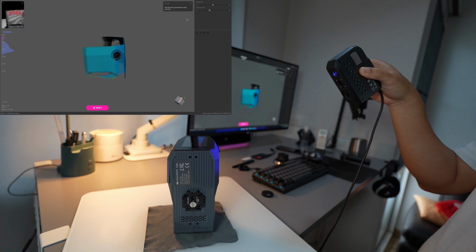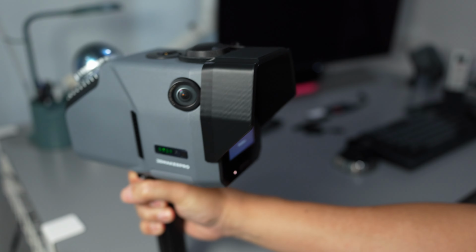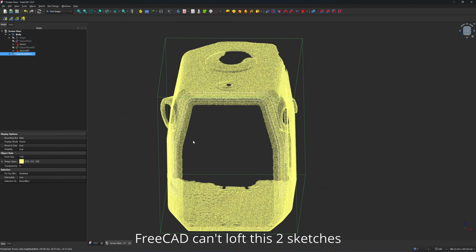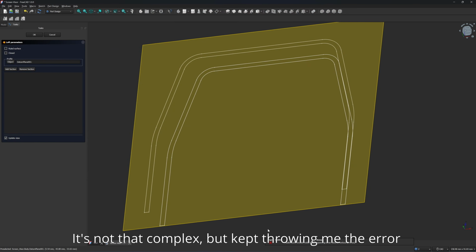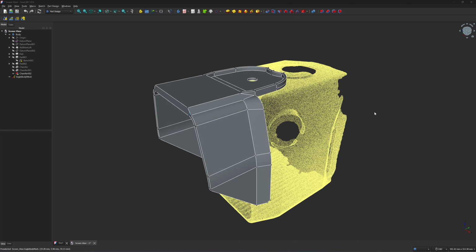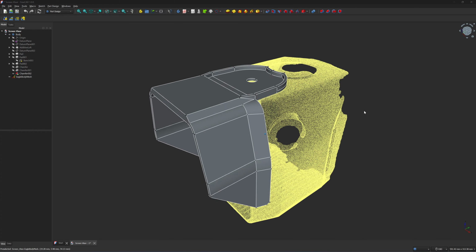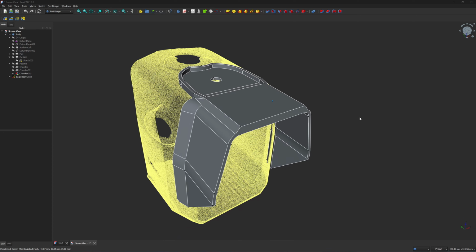Okay, so in the previous video, I made this LCD hood by using Autodesk Inventor because I have tried with FreeCAD and it didn't work in the loft function. But I found out later that the implementation of this loft function in FreeCAD is different from other CAD software. Now I can create the same LCD hood by using FreeCAD. So in this video, I'm going to do a step-by-step demonstration, starting from importing the point cloud and creating this LCD hood for 3D printing in the FreeCAD version.